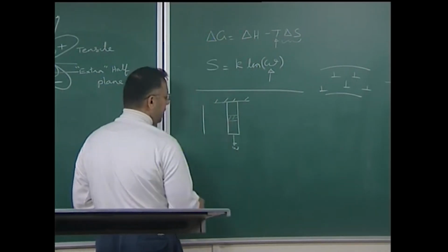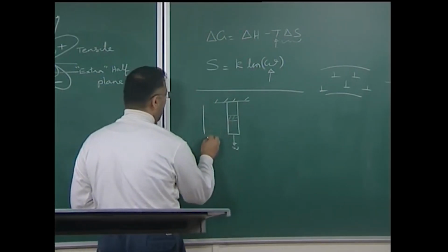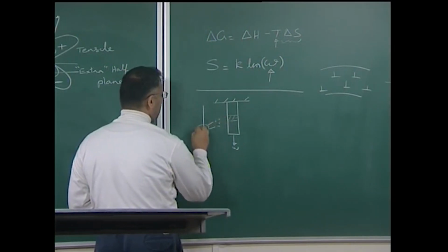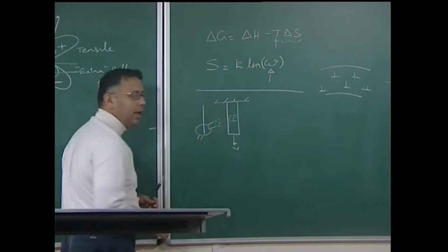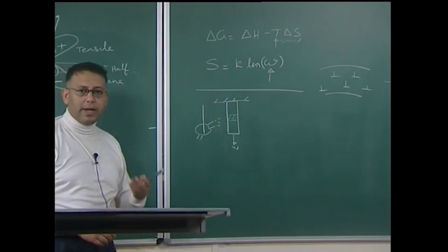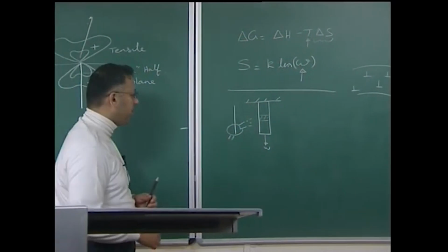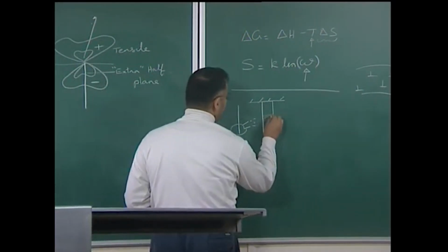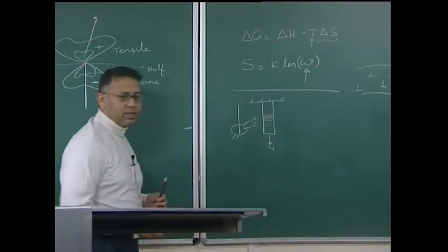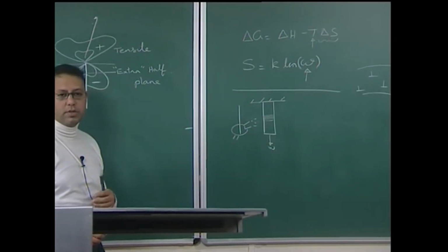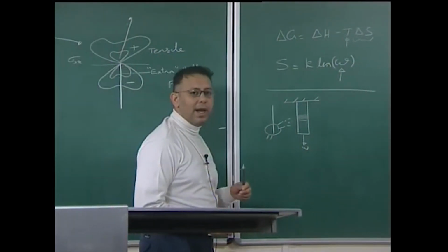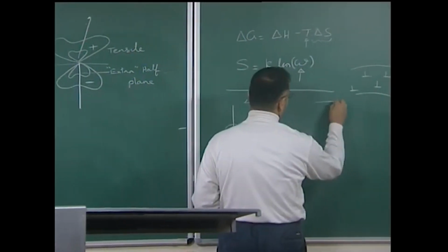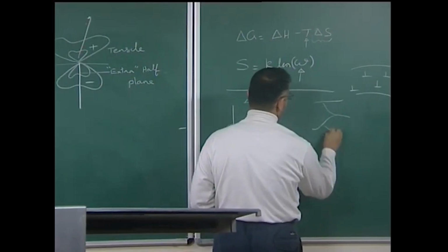On this edge surface, of course, I may want to heat the system by, for instance, a hair dryer or one of those things, so that I give some hot air to the system to actually heat up and therefore improve the kinetics. So, the kinetics of the process which I am going to do is going to be fast. Then I can rub a little bit of gallium on the edge surface, the pickled surface. Now, what happens when you put gallium onto this surface is that, suppose I am talking about now on the microscopic scale, this is my grain boundaries.